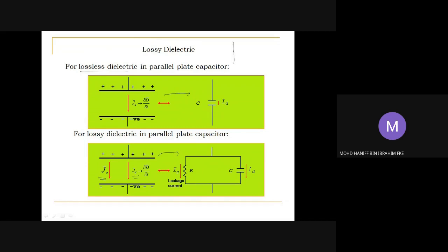So we have the phasor graph for both the displacement current, ID, and the voltage, in this form, in which the current of the capacitor will always lead the voltage by 90 degrees. ID stands for the current of the capacitor, and V is the voltage of the capacitor. This is for the case of a perfect dielectric in use.